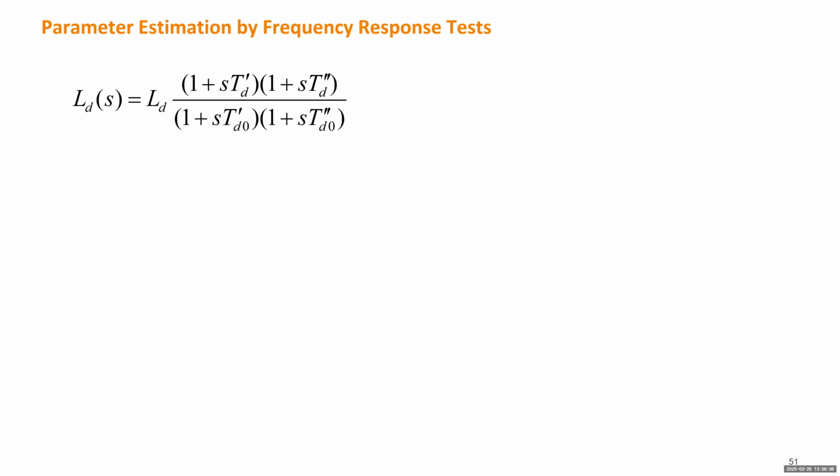So even if they gave you those initial values for those time constants, you still may want to do your own test to verify or validate those parameters. And also when you use the generator for long enough time, some parameters will shift, will maybe float to some other values because of aging effects, because of different operating environments. You still want to do testing.